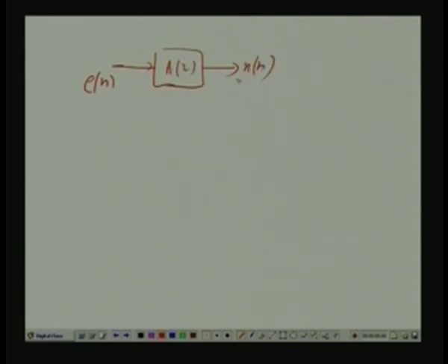We are considering either AR modeling or the linear prediction problem. In any case, we have got this equation, say a pth order problem, into En. If it is a linear prediction problem, En is orthogonal to the past p samples, that is xn minus 1, xn minus 2 up to xn minus p.